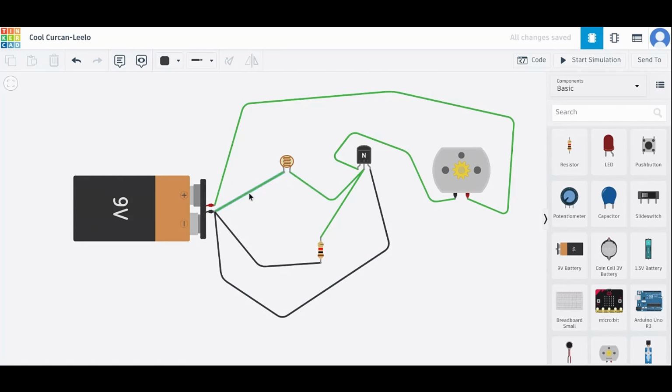So what we noticed, we couldn't really control the current in the motor directly using the photoresistor. So now we are rather going to control current in the motor. That is, we are going to use a transistor to turn on and off to behave as a switch. So now the circuit is 9 volts connected to the motor. And then that switch is turned on and off by what is there at the base.